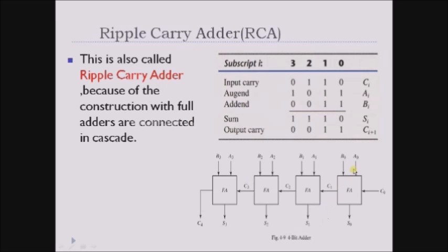There you can see a and b are two operands holding 4-bit numbers, that is a0 to a3 and b0 to b3. All these inputs are given directly, at the same time, to 4 full adders. Along with these inputs we are giving one carry, and that carry is 0, because the initial carry would be 0.